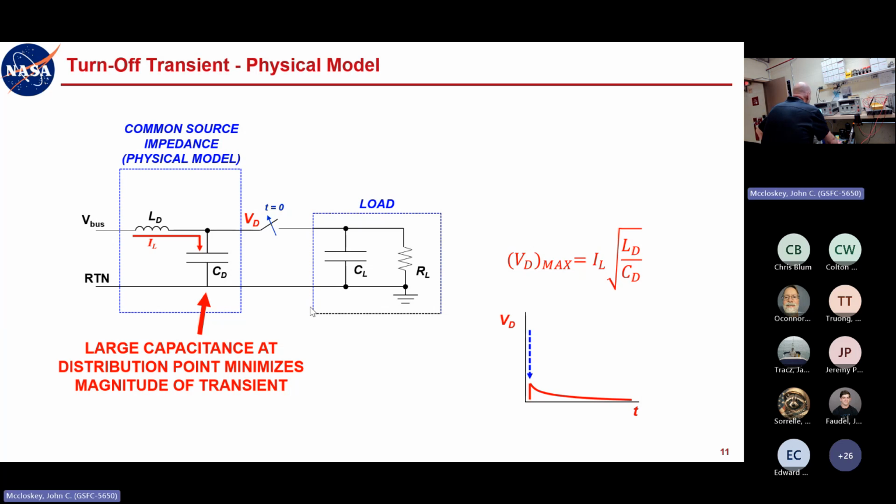I mean, very easily. And if your starting current is even higher, and if your characteristic impedance is maybe pushing 100 ohms, it's not too hard to see that you could have transients of a couple hundred volts. So when you see this stuff about a transient of 200 volts, and you think that's ridiculous, how could we possibly have that on a 30-volt bus? You can very easily, if it's dominated by inductance.